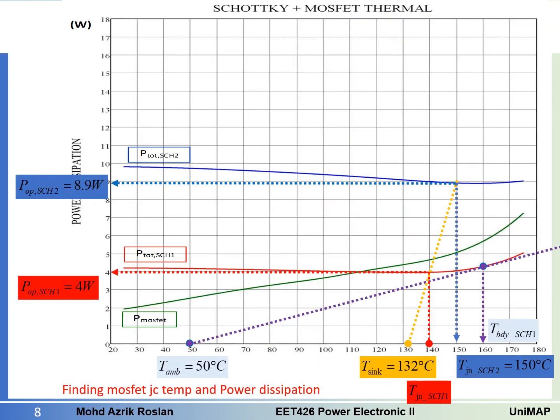So that one we have to draw here. This is the temperature of the heatsink, and we know that at this point this is 132 degrees C. So if we want to have the increment of 3 degrees C, it is 132 plus 3, which is 135, which is in the middle of this box from 130 to 140.